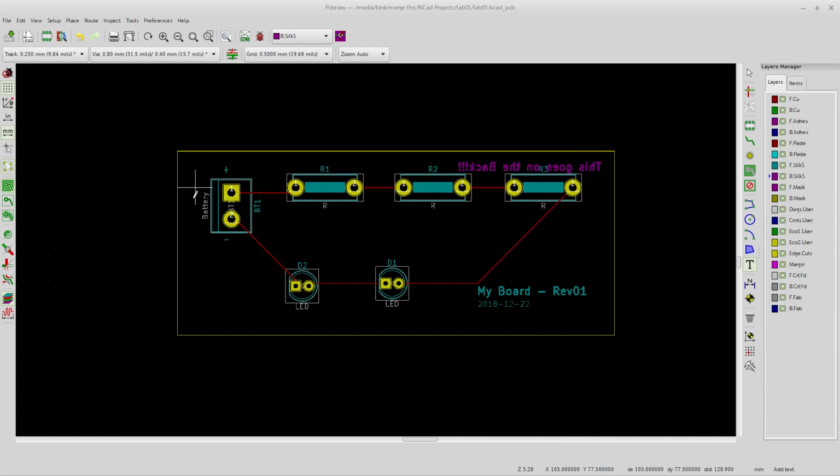In your footprint, when we're developing footprints in another video, you want to make sure that you check the data sheet again. We are going to be living at DigiKey and Mouser and any of those other places that have our data sheet, so we can go through that. We're going to see all the electrical characteristics that we need to look at, but also all of the 3D documents. You need to know not only the size of the part, but the size of the pin. When you look at something like a MOSFET pin and go, oh, that's not very thick, well, it's wide, and you've got to accommodate that as well.